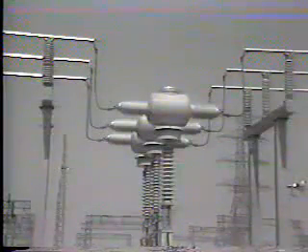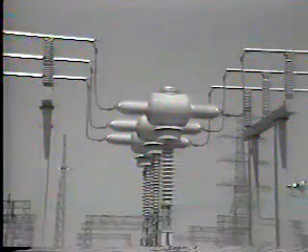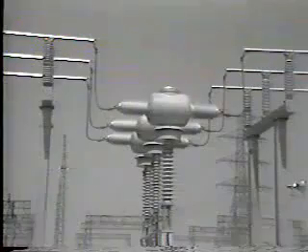Another type of arc quenching is through air blast, as in this 345 kV breaker. As you can see, each phase has its own interrupter mounted on insulators. As it is insulated from ground, the tank is known as a live tank. Each of the phases is equipped with its own separate tripping coil, and they are usually, but not always, wired in series.